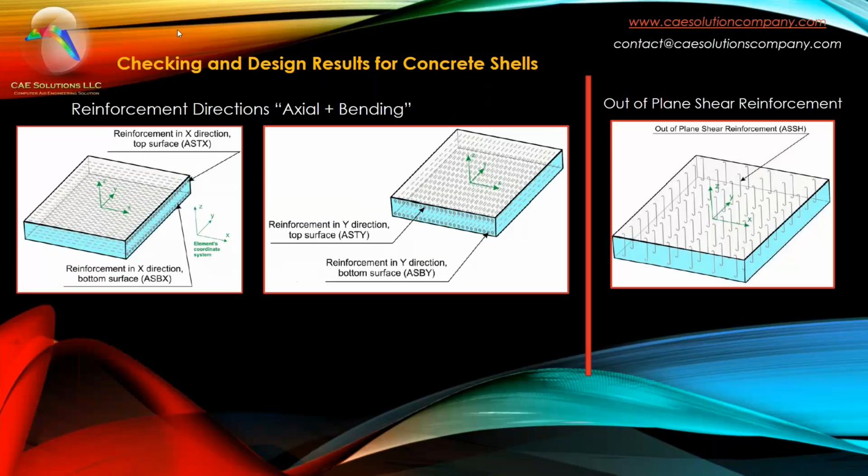Again, as we refer back to the criterion definition, we see here that the load would be reinforcement in the X direction for outer plane loading, reinforcement in the Y direction perpendicular to X for outer plane loading, and for the shearing strength of the plates, we have the mid-plane loading of the shell representing the elevated slabs.